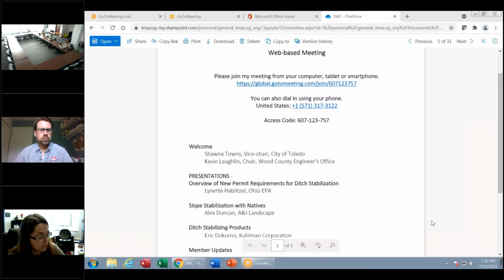That's something I would recommend talking with your district stormwater staff about specifically, because I think this ties into the question of when is it a ditch and when is it waters of the state, or when is it an MS4, and sometimes it can be both. So I would take the specific situation, if you have that question, and run it past the district staff, and we can help work you through that scenario.